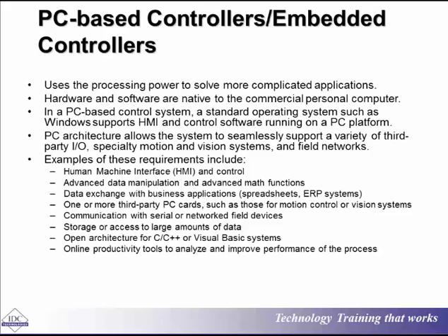When the requirement does become a little bit more than straight inputs and outputs, the idea of using a higher level type of mathematical computation is an overhead generally on most PLCs that affects its performance. So hence there is a trend, a need to go for more complex independent computing devices, and that's where the terminology including embedded controllers and PC-based controllers have come to the fore.